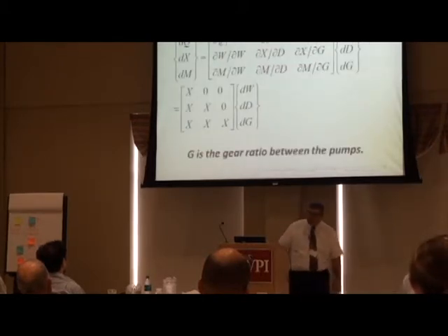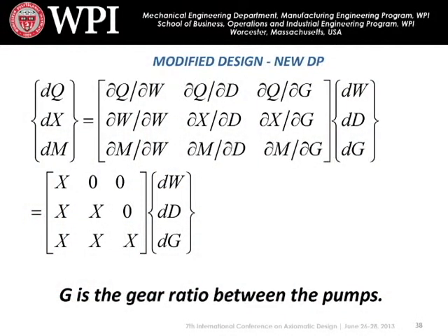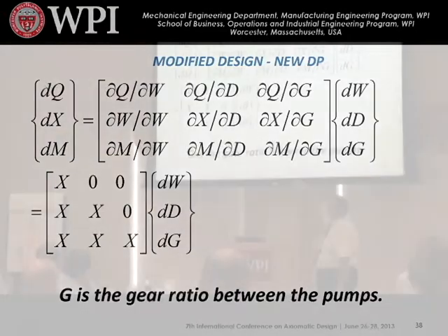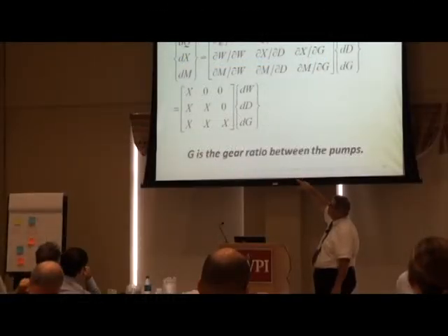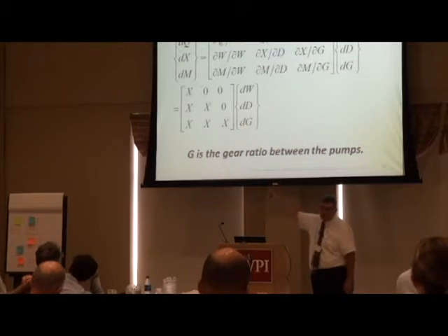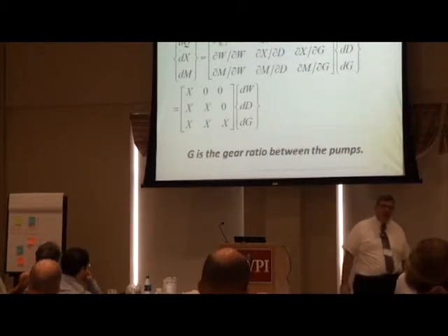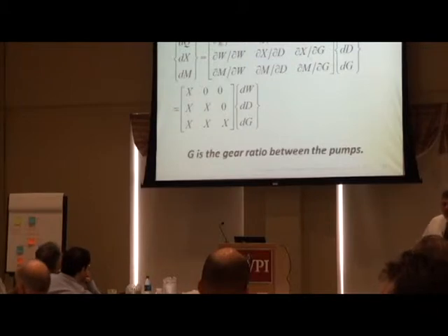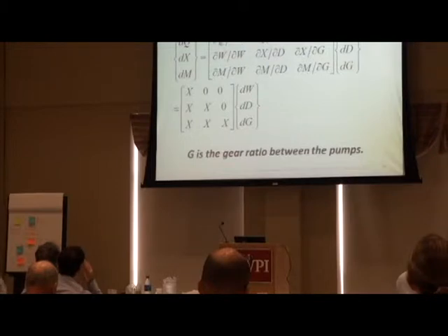And so now we have 3 DPs fulfilling 3 FRs. And so if you look at the matrix on the bottom, this doesn't look like any of the previous matrices in that we have interactions between all of the FRs and all the DPs, except that one DP affects one FR, one affects 2 FRs, and one affects 3. And so that would tell us that there's probably an order of adjustment that we have to go through in order to get the system to work right.